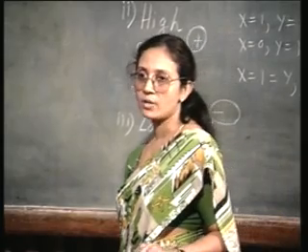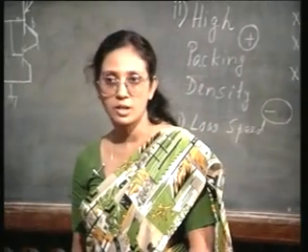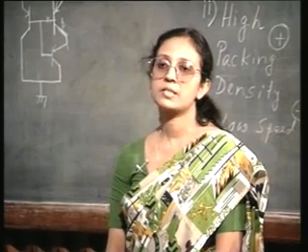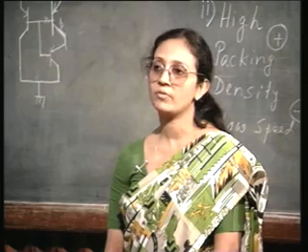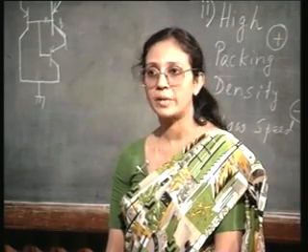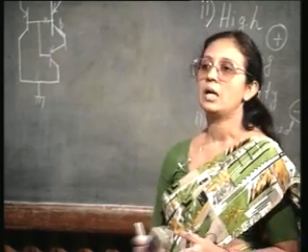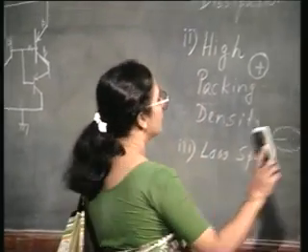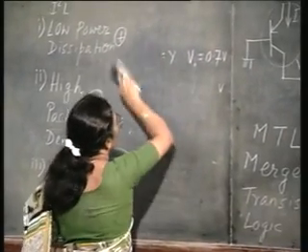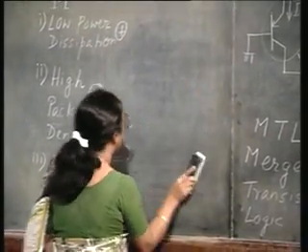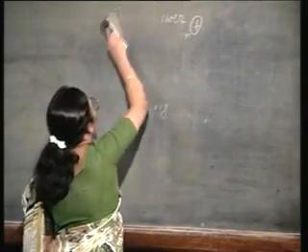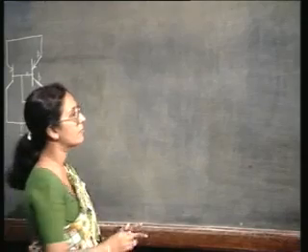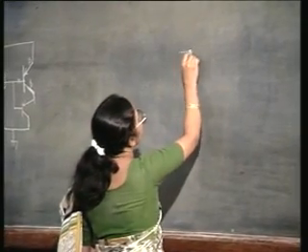And of course, as you have seen in the case of junction isolation compared to dielectric isolation, if instead of junction isolation we have dielectric isolation, it is always better. So, a more advanced I square L design will be to replace the N plus collars by an oxide. So, in that case we will have a circuit like this.